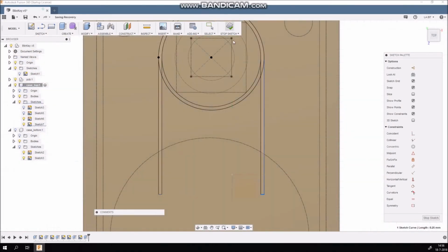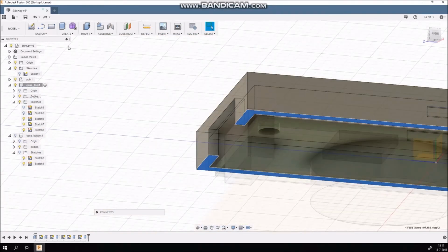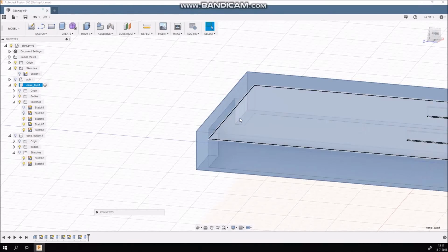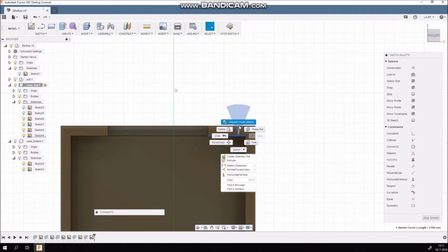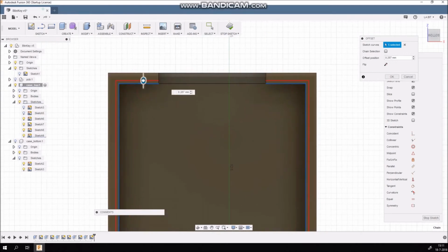We're going to make it so you can actually put these boxes together and it will fit. Therefore, go to the bottom of the top and select the outer shell again. Select the contour and make a new offset. I want this to be half of the thickness.